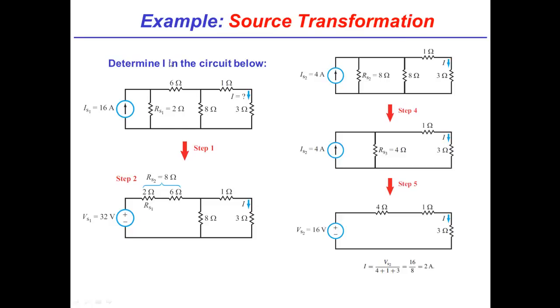And that's all true. You could have collapsed the circuit this way, but then you would have lost what I is. Because what we wanted to solve is what the I through this branch is. So we needed to keep this part of the circuit intact, so to speak, and transform over from the left. So there's a little detail, but it's one that I've been asked a couple of times when students see this problem and are collapsing it. It's because the problem forces you to solve for I that we begin to transform from the left. Should we go on? Yeah, let's go ahead.